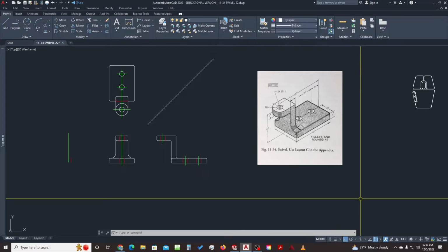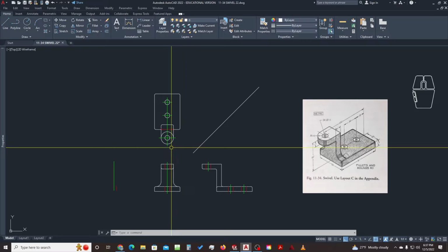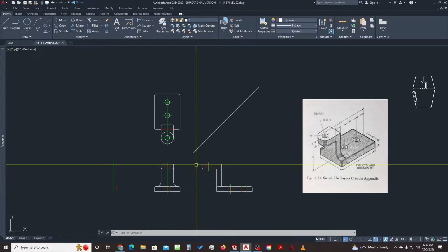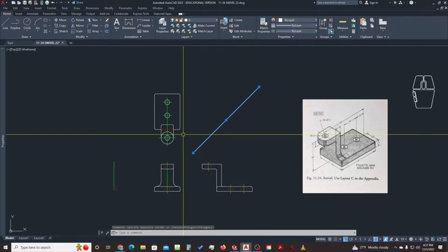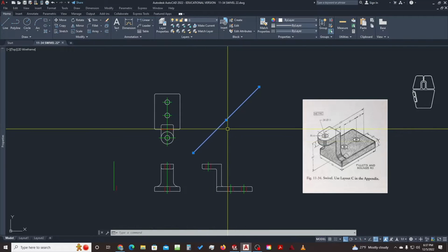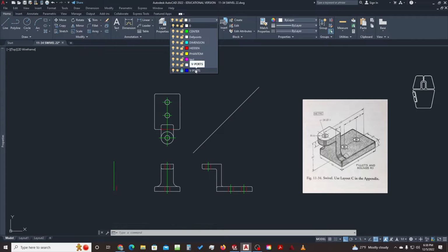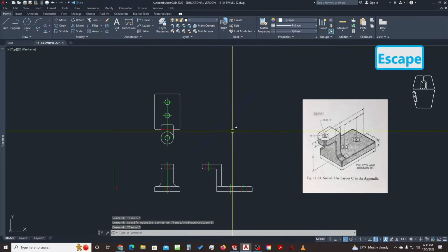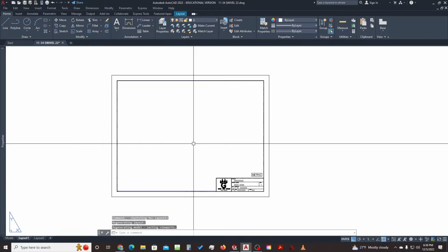Okay, so to make a drawing of this part, at this point, once you've finished laying out the different views of the part, I do want to get rid of this 45-degree line and any other horizon lines. And instead of actually removing it, what we're going to do is throw it on a layer for viewports. So this viewport layer does not show up when printing. So we're just going to click that and then go change the layer. And so we'll be able to see it here, but when we go to print, it won't show up. Head over to layout 1 to find your part.